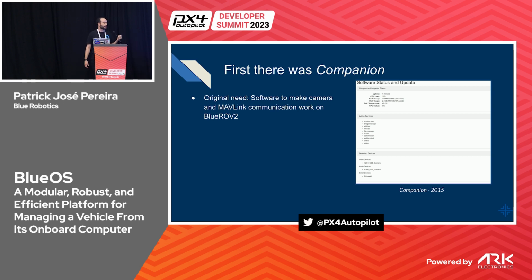The video could be, at the time, any USB camera that supports H264 encoding. And we had this limitation, like you could only use a single camera or a camera with this feature, because H264 encoding was what was being used. We had a fixed GStreamer pipeline. We tried to make it smart, but it's kind of a bit hard to do when you deal with raw GStreamer pipelines. And at the time we used MAVProxy to do all the routing process of the Mavlink.